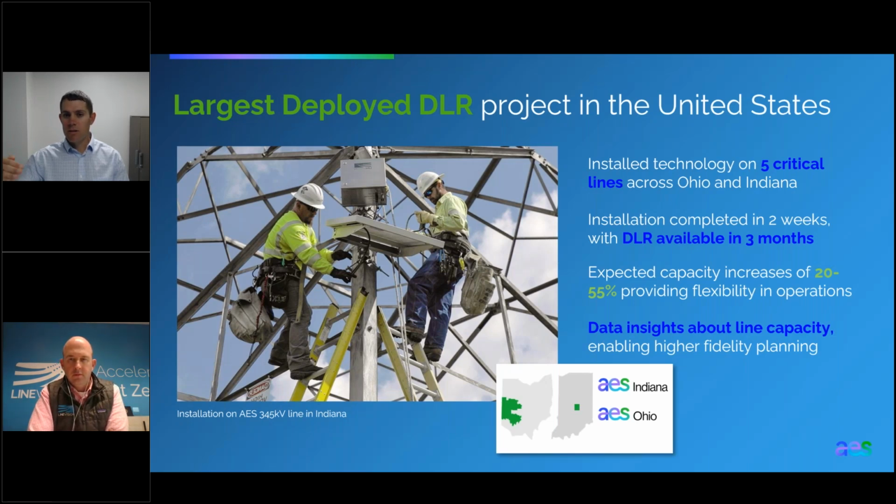So again, what's the vision, what are the problems you're facing, what are the challenges, and then it was identifying specifically which lines limit our capacity, right? And it may not be just a line. You may have another most limiting element, such as a wave trap or a switch at a substation or a midline switch that could be holding back 20% of the line's capacity, right? So it's doing that detailed review of the circuits that are limiting your challenges, like the ones on the 69 kV system around this Honda plant, and identifying those problems.